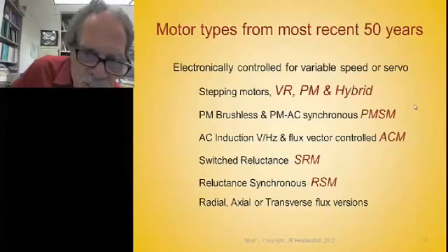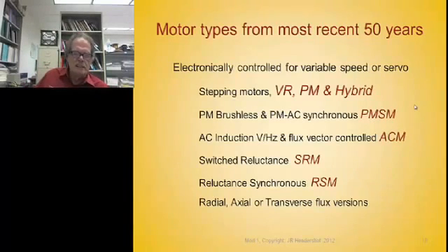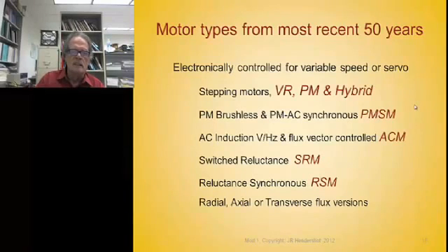You could change the frequency and change the voltage, and you can put all sorts of feedback systems on the motor, such that you could control a number of revolutions or part of a revolution, for what they call servoing for incremental motion.